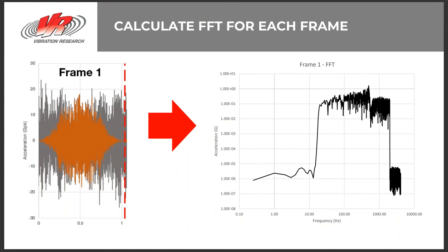Windowed time data is used to calculate the FFT. Basically, the FFT is a mathematical function which transforms the signal from the time domain into the frequency domain. This linear transformation gives us the ability to observe the frequency content of the time history waveform. There are many use cases for the FFT in signal analysis and processing. Most importantly, it shows what frequencies are present in a signal and at what proportion. This can be used to determine what frequencies are being excited by a particular section of time, the peak acceleration of that particular frequency inside of a windowed frame of data, the distribution of peaks and harmonic content, etc.